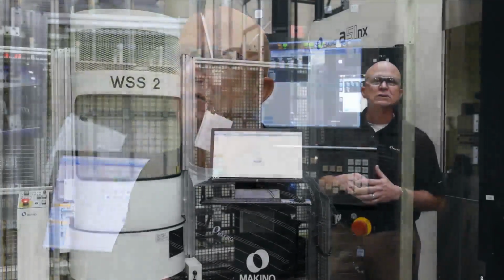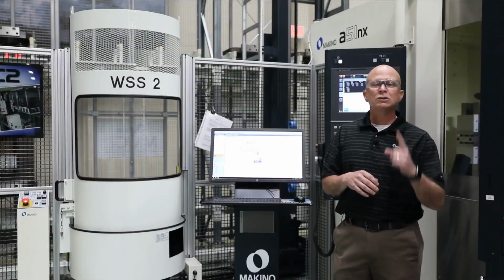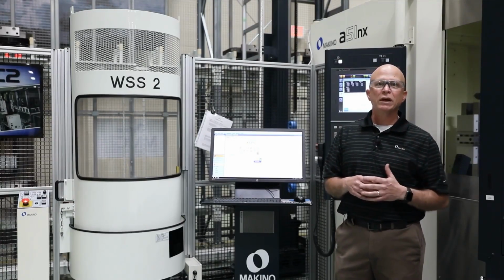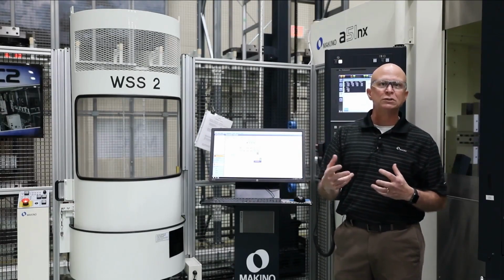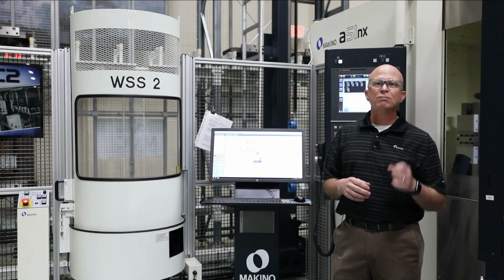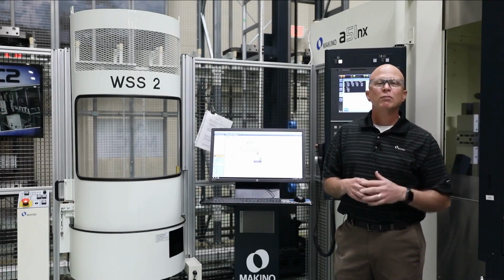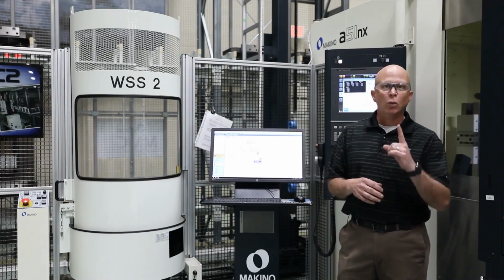Then the second one you're going to see is the optimized, where we start and end with the nest closest to the tool changer. Then finally, the third demonstration in this series, I'm going to show you multi-axis positioning. Now, just a note on multi-axis positioning, you have to be careful when you're implementing rotations and positioning. You have to fully prove that out so you don't crash your machine. So let's run this first one, and then we'll pause.